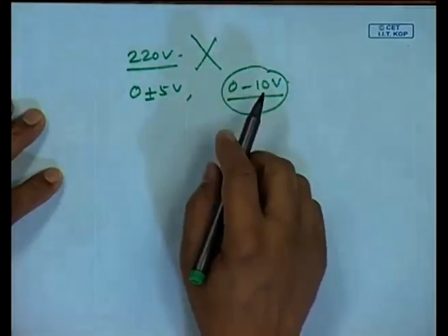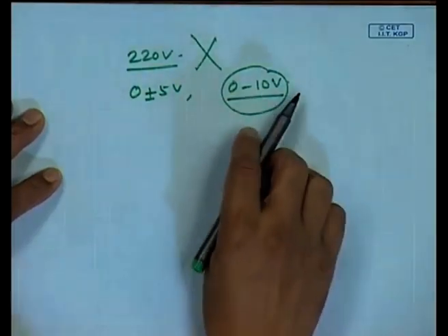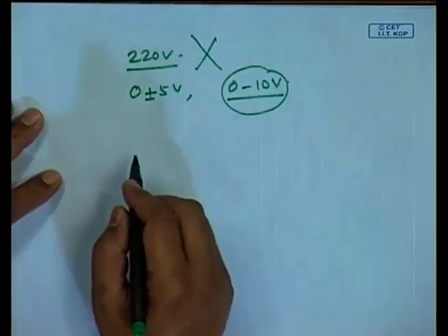Okay. Sometimes, as I was telling you in the example of a thermocouple, the signal levels are so low that they need to be amplified before even doing the A to D conversion. So, some of these cards can have an amplifier where we can set the gain, so that we can increase the voltage.